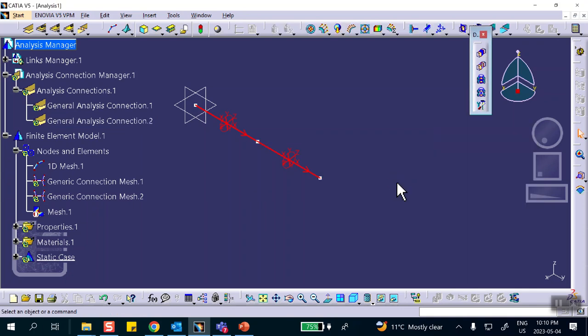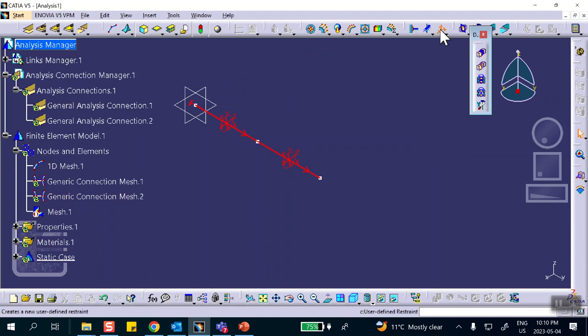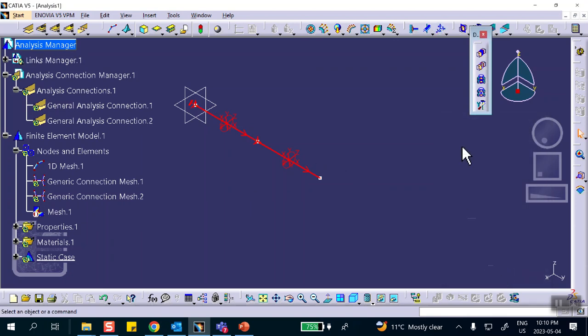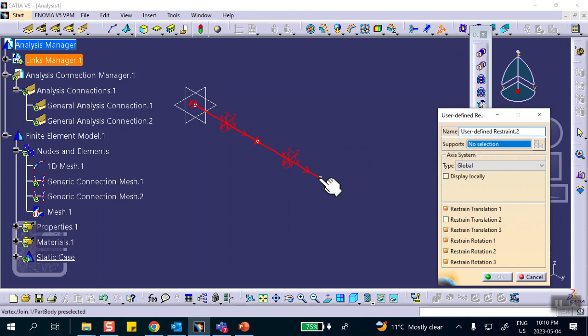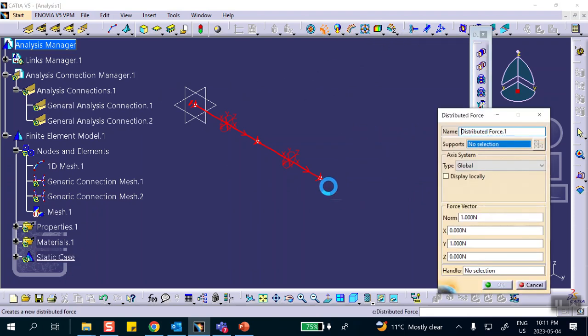Okay, good. Now apply the restraints. So restraint is right here. This one is clamped. This middle node, middle point, does not move. It does not move in any direction but Y. And the other one, same thing. Now, because I want to assess the possibility of having made any mistakes, I'm going to put a static load of 1 Newton here, force right there at this point, 1 Newton direction Y.